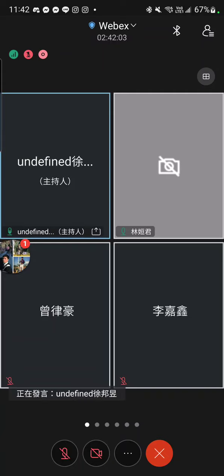This is the I site in the crystal. That means all this space, all the I sites in the crystal, right? Of course, you change your capital N to N_I because you have a different interstitial site compared to the crystal site, right? This cross spot is the crystal site, but now we are thinking about the interstitial site. So we need to use the interstitial site number to calculate that.